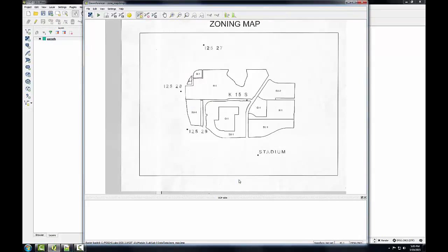And on the map, there are parcel boundaries and 5 points, signified by these black dots. These points are benchmarks maintained by the National Geodetic Survey. To georeference this scanned map, I'll create control points at these 5 locations. The plugin will develop a georeferencing equation based off the set of source and target coordinates at these 5 locations. QGIS will get the source coordinates from my mouse clicks.